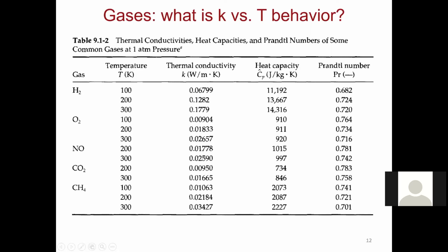Okay. Something to also look at is the Prandtl number within this material. This is the momentum divided by heat transfer, in terms of the molecular motion. I can see that this is roughly 0.7 for gases, so it's relatively close to 1. It seems that the momentum is going to transfer slightly slower than heat. And this is just for intermolecular interactions, but they're give or take on the same level, if you will.